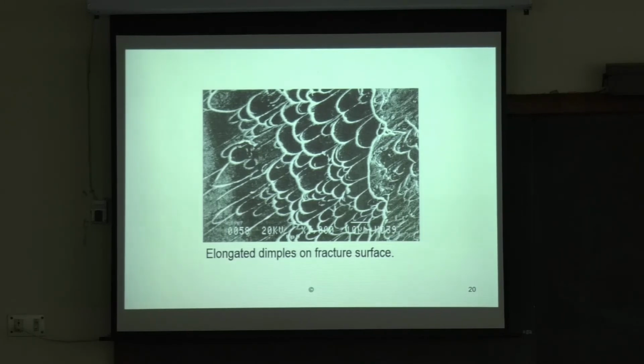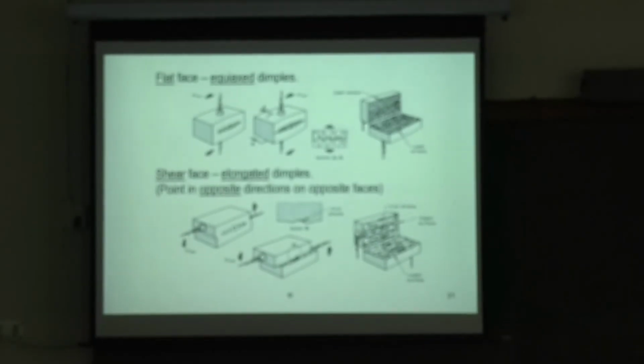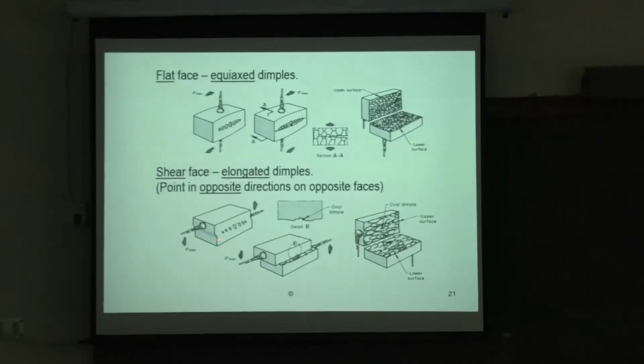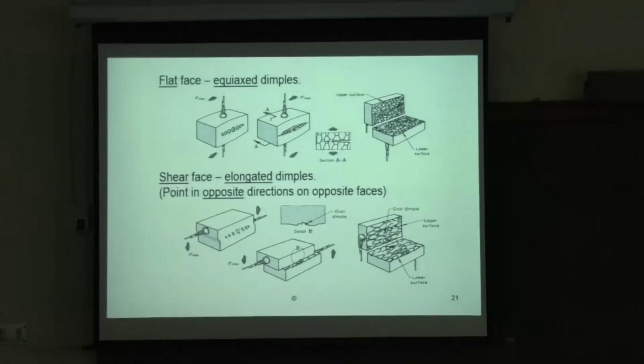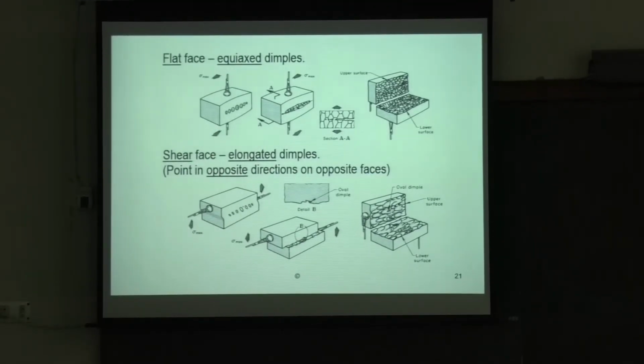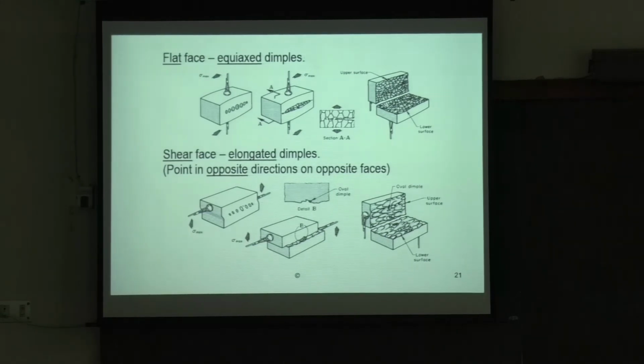The fracture keeps on continuing, and the flat surfaces are more related to shear fracture. So here you can see what shear fracture is. This part is shear. What is shear? This goes that way and that goes this way. Shear fracture is still a ductile fracture.